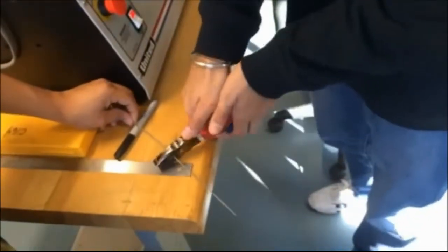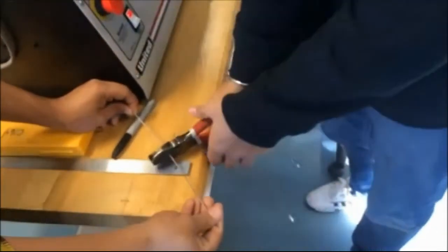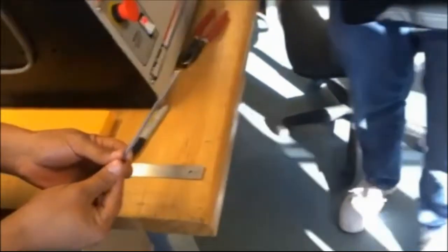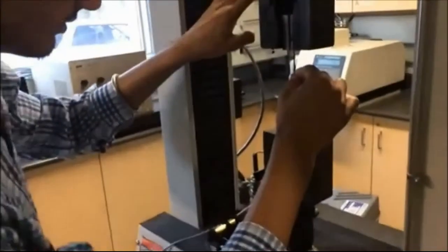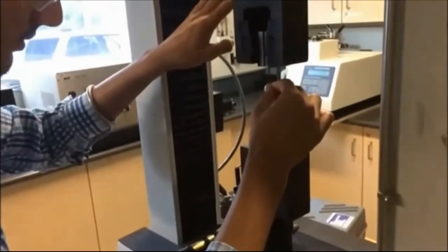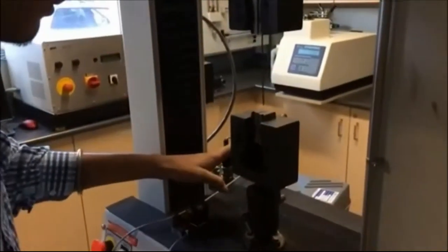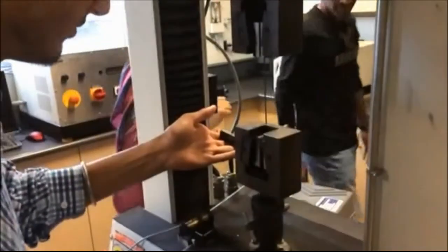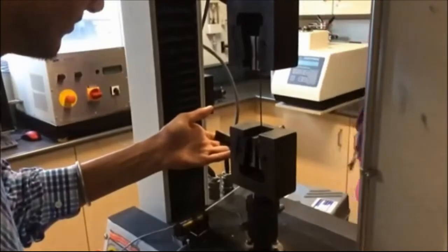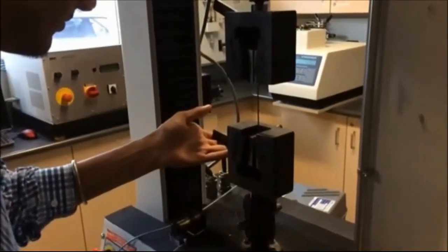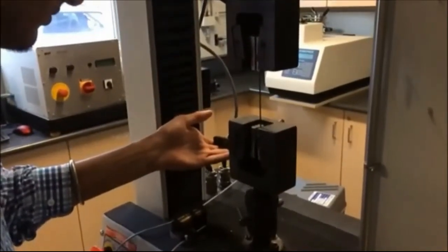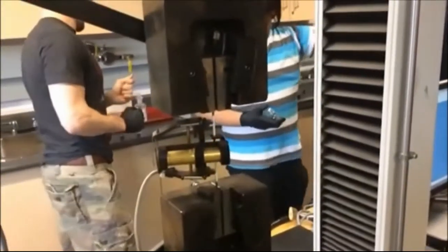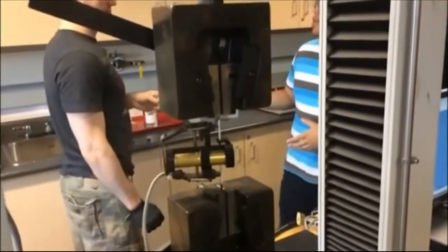The first part we put on the UTS tester. Then the diameter of the spoke is taken. With the help of the datum program, a run is started to load the sample. Then we use the knife edge extensometer, which was pinched onto the sample at the gauge region which has been painted on the two sides of the sample. After that, we check that the force, extension and position have been made zero. The extensometer was removed when the screen popped up.